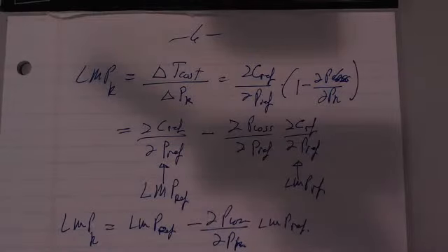And anytime you do an optimal power flow on a transmission system with losses, and we'll see that in your homework whenever you run the ACOPF that I'm going to let you use, it results in different LMP, even without any constraints on lines. There's no constraints on lines. You get a different LMP for every bus because the loss effect is different around the system.